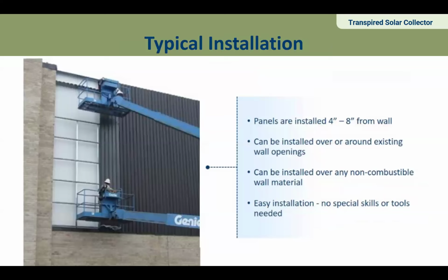So here's the crew installing the panels as they go. And typically when you're seeing the system installed, it's going to be what's called an exposed fastener system. The name is, as it implies, you will see the screw heads through in the valleys in installing it to the girts there. The reason you go with that type of product typically is because of the structural capacity that the panels have, so you can space out your framing a little bit further apart. But you can have any number of structural panels, concealed or exposed fastener panels, as a part of this system.